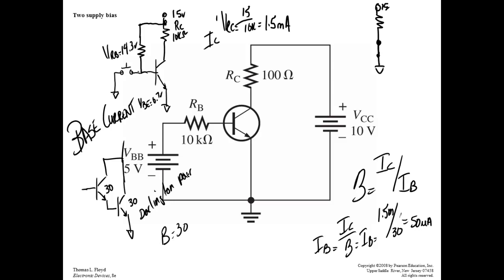So if this has got a beta of 100 and that's got a beta of 100, that's a lot of beta, right? You understand that? So Darlington pairs. This is very popular, especially in saturated switches. So we get extremely high betas just by doing what? And this is what the guy was showing y'all on the video. I don't know if you remember. He took the base out.